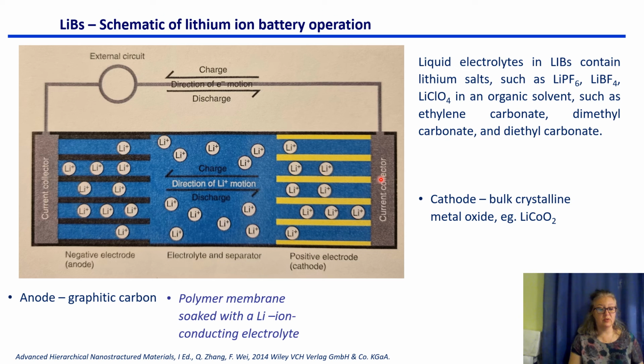To summarize, during discharge, lithium ions carry the current within the battery from the negative to the positive electrode through the non-aqueous electrolyte and separator diaphragm. During charging, these reactions and transports go in opposite direction.